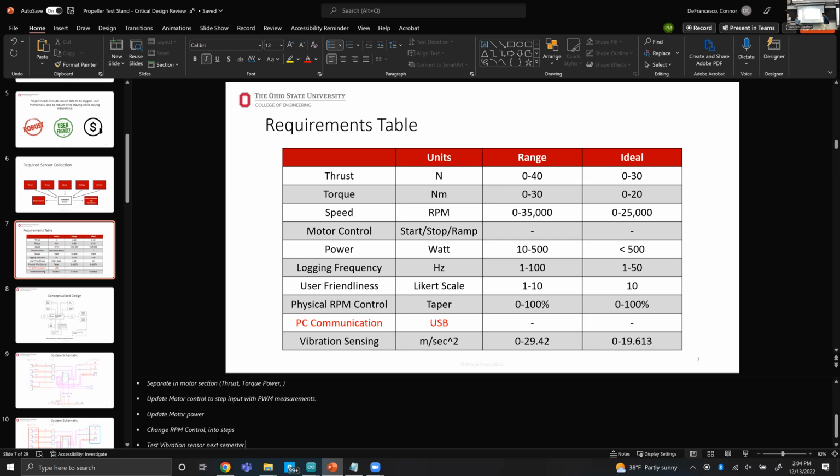Curious, what were your biggest challenges with the PCB design and development? The components are very, very small, and I was just trying to shrink everything down. The first time we designed it, we made a pretty stupid mistake where we connected the transmit of the ESP32 to the transmit of the USB UART chip. You can't connect TX to TX, or RX to RX.